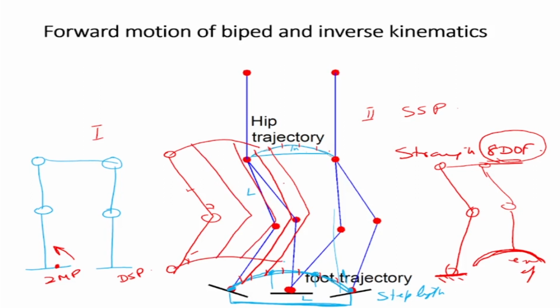So you can very easily solve the inverse kinematics of this because it is 2 links only. Instead of trying to solve for an 8 degree of freedom system, which is a redundant system, you will not be able to solve it. You will get infinite solutions and all kinds of things. It is much easier to solve from geometry.